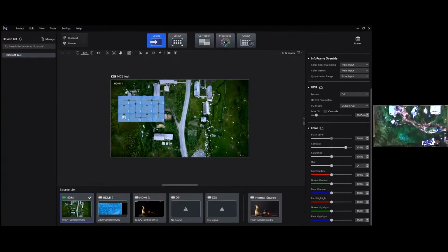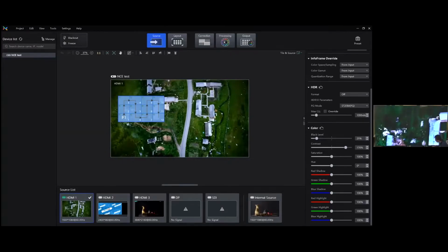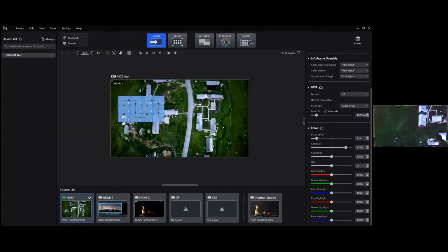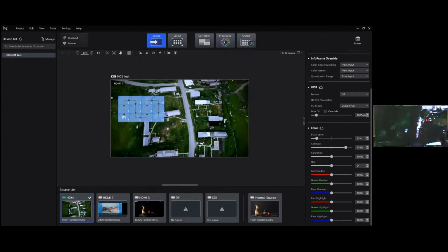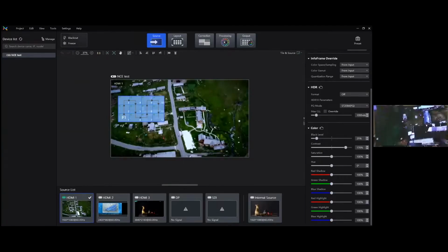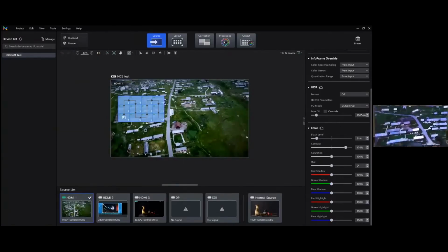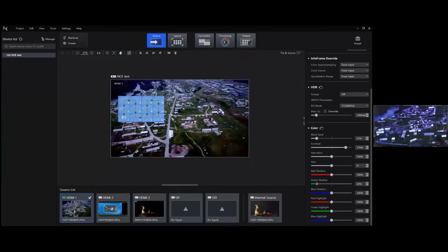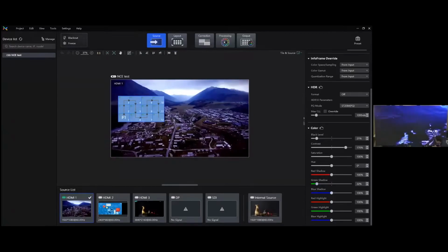Besides that, we also can do the RGB channel shadows and highlight settings separately. So we can observe this content displayed on the LED display, and find that there is a little bit more green. If we don't want the green color so strong, we can just lower the green from the video source.